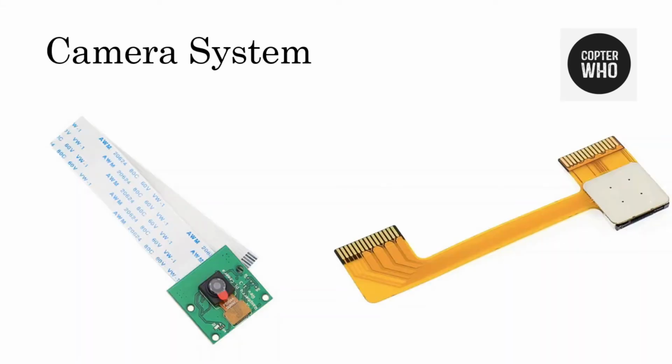The drone uses a pair of cameras connected to a camera scheduler to avoid objects. The algorithm works out the depth of objects on the screen by comparing two different images, one taken from a left camera and the other taken from the right camera. First, the cameras are calibrated so that the images taken will be aligned perfectly when an error correction algorithm is applied to them. This is necessary as the two cameras will not be identical in reality.